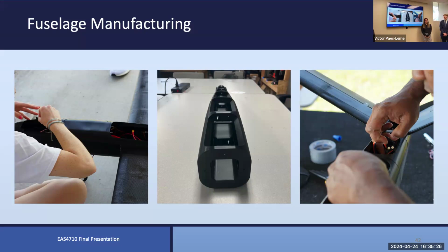Ting for the suggestion of moving the fasteners between the fuselage sections closer to the longeron for some of those pieces. And lastly, the access hatches, as stated earlier, we do have 6 of them attached with Velcro, and these proved to be very helpful in manufacturing and assembly, especially in between test flights where we were able to fix things or check things when we needed.